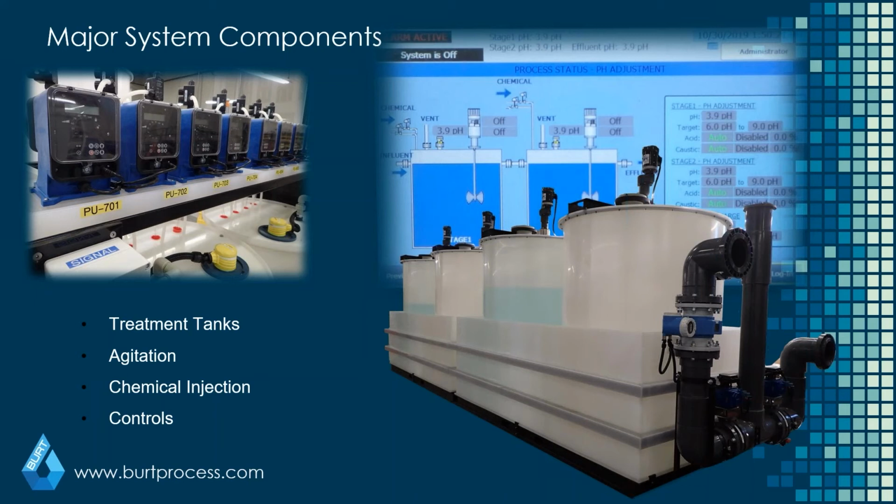As a result, if you have a 100 GPM system, you could be looking at a containerized system that has to hold a 2,000 or 3,000 gallon tank, have proper access to it, have the reagent chemicals, have the control panels, and then have to be able to meet all the different requirements, whether it be NFPA 79 or clearance for lockout, tagout, or chemical changeout. And this is really what drives these systems to be built, obviously, in much bigger applications.